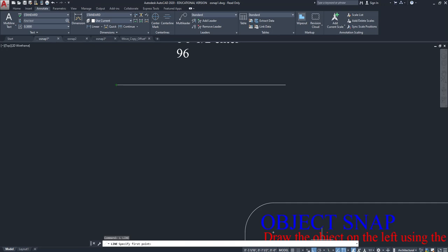We have a lot of drawing type snaps where endpoint, midpoint, center, node, quadrant, those are all going to hit on a line, and they'll show you a little symbol on a piece of geometry. Intersection and extension are going to show you where imaginary things happen. So if I hover and I do not click, and then I move my mouse down, there we go. Now as I move down, if I click where that invisible thing is happening, those pieces line up.